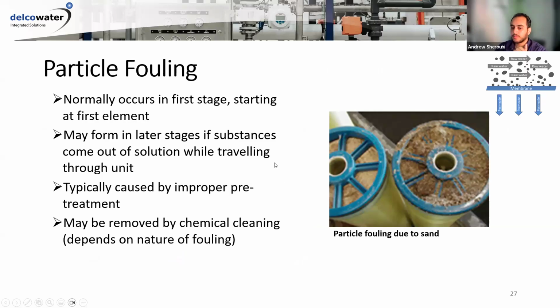Just so you know, fouling and treatment are different. If you get any solids in an RO membrane, the RO will stop it. It's not going to go through, but it will coat or cover the surface of the membrane. I have the diagram here again of cross-flow filtration. This kind of self-cleaning action works with dissolved contaminants and with very low suspended solids in the water. But if you have high turbidity going directly into an RO, you get really heavy fouling and it just clogs up the pores of the membrane. And because you're using this cross-flow filtration, you just don't get clean water coming out.